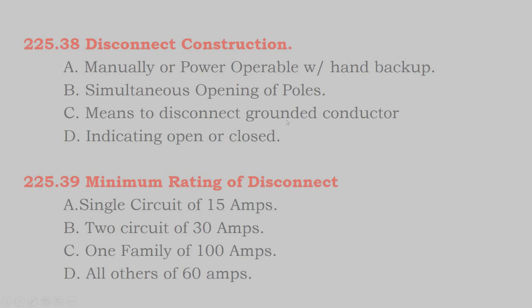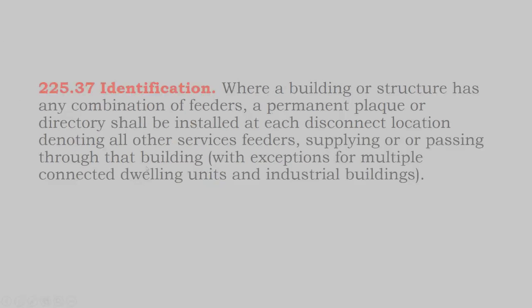Sometimes, like the requirement for the knife switch disconnect at the residential level, that knife switch disconnect is not part of code, but often the inspectors are treating your residential arrays kind of like distributed power systems, and they're used to seeing knife switches on distribution stations and substations, so they like to see them on your solar array as well.